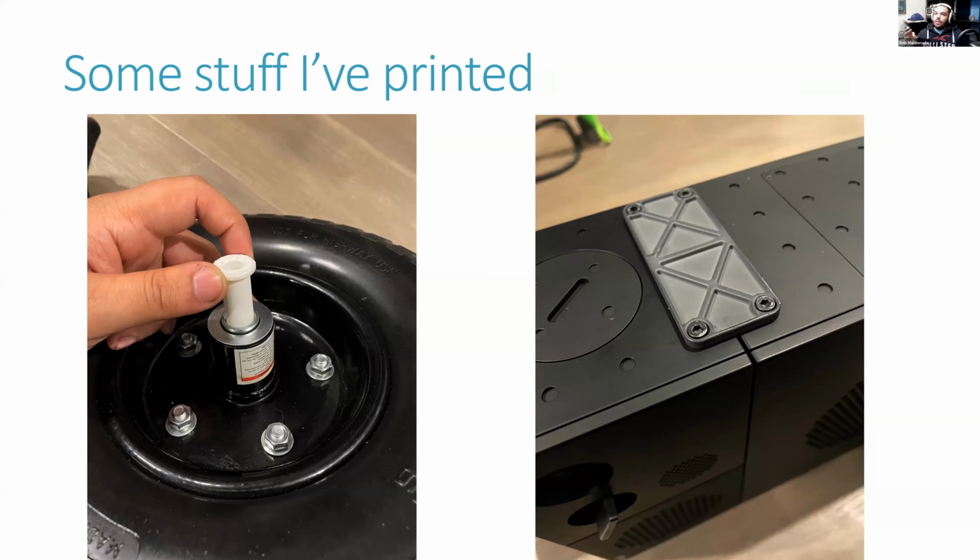So if your curves are critical and your fits are critical, be sure to crank it up. Though keep in mind that that will result in larger file sizes, larger load times, larger processing, etc. So it comes with a grain of salt. If you're just 3D printing a cube, don't worry about it so much. But if you need a specific interference fit, and you're working on that process, be sure to crank up the mesh resolution on the STL.